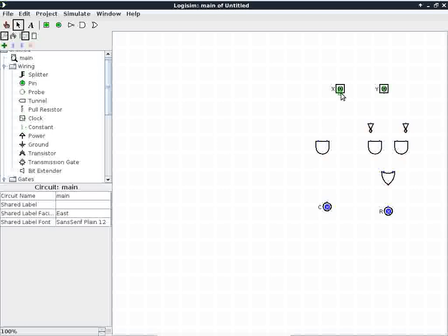be the connection point. At this point you can click the mouse, hold down the left button, and then draw a line to wherever it needs to go. In this case, I wanted to go to the left side of the AND gate right below that. So I'm going to stop here and then drag another line and then finish the connection here. Is that okay so far? Okay.